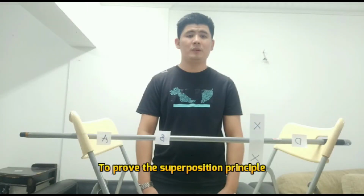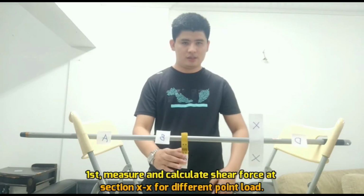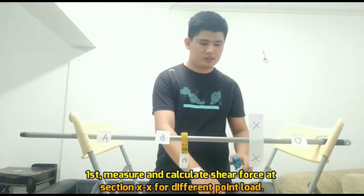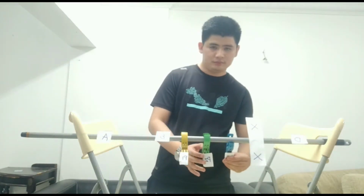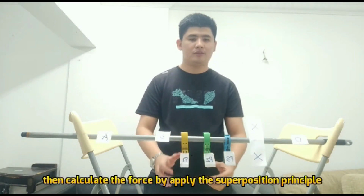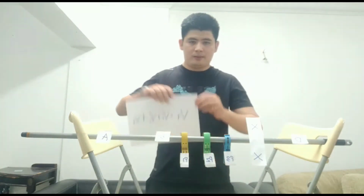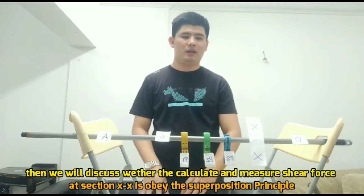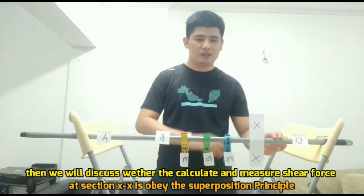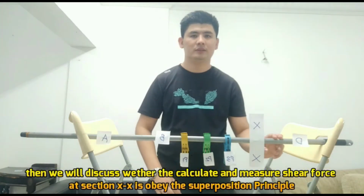To prove the superposition principle, first, measure and calculate shear force at section XX for different places of point load. Then, calculate the force by applying the superposition principle. Then, we will discuss whether the calculated and the measured shear force at section XX obey the superposition principle.